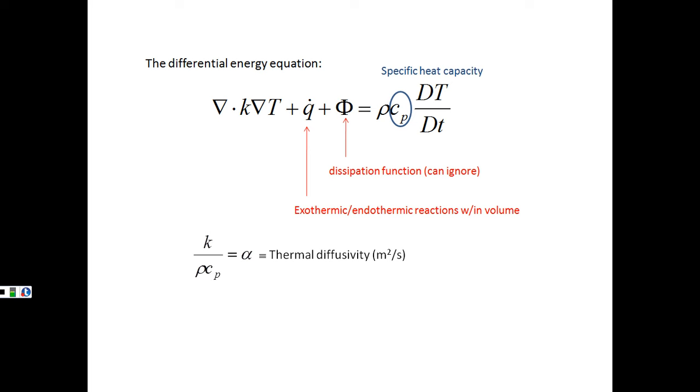Here, we need to account for different material properties such that we're taking into account the fact that our density changes at different temperatures. Specific heat capacity is something that's consistent. It's a defined property of the material of interest. And our thermal conductivity, which can also change as well. That's why it's actually inside that divergence term on the upper equation. So by taking into account the conductivity, the density, and the specific heat capacity of your system of interest, this new alpha term in this particular form for this equation will then be representing our analogous diffusion coefficient.